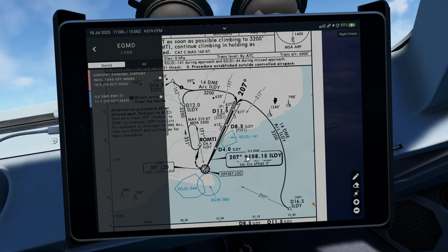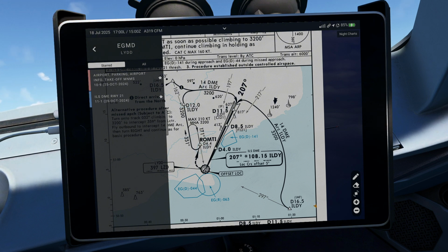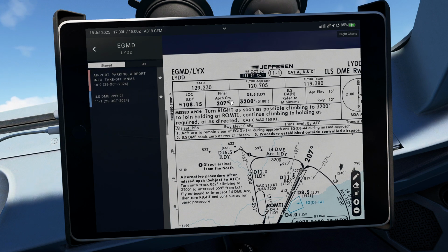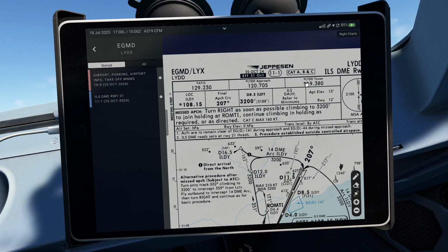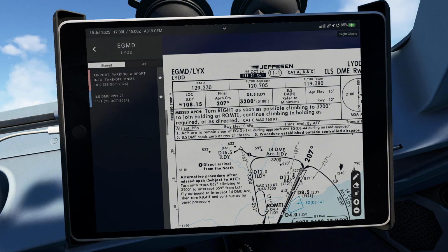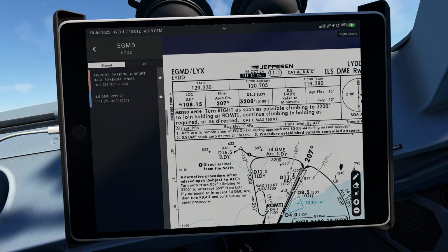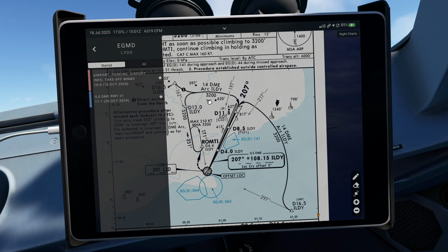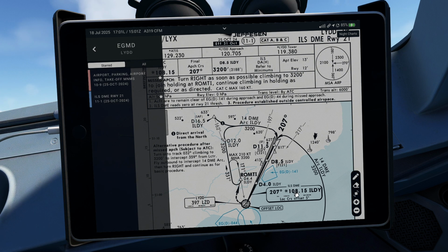And the last reason is that, in some cases on charts, there is an asterisk next to a navigation frequency such as ILS, VOR, localizer, and maybe communication frequencies, for example ATIS, approach frequency and tower frequency, as you see four asterisks here. They show that the facility operates on request, part-time, or on a limited basis. It means non-continuous operation of the facility for the communication frequency or localizer.